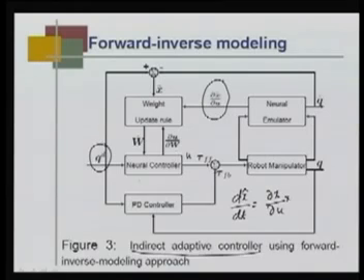The neural controller is characterized by a weight vector w, and u, the output of the neural controller, is a function of this w. It is not a function of the PD controller gains, because they are fixed, so they do not affect this q hat. What affects it are the weights, because these are changing in the neural controller. So dou x upon dou u, again dou u upon dou w. u is the output of the neural controller, which is characterized by the parameter w, and the input is q d, which are all known. So naturally dou u upon dou w can be easily computed from the neural controller, into dw by dt. This is the weight update law.